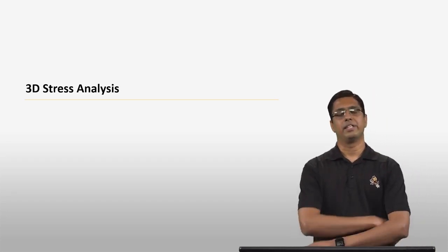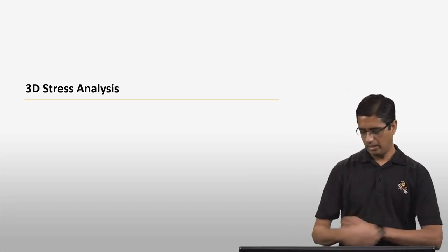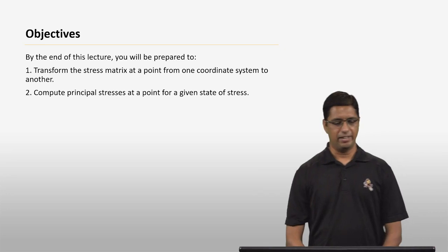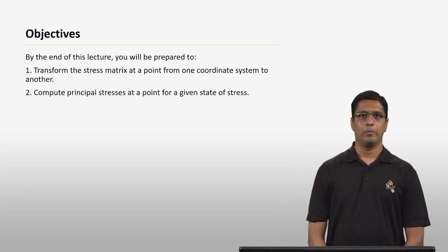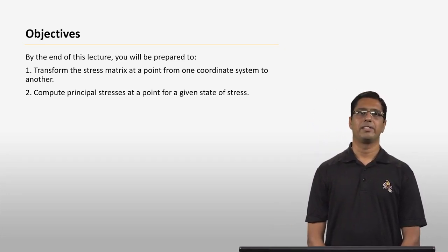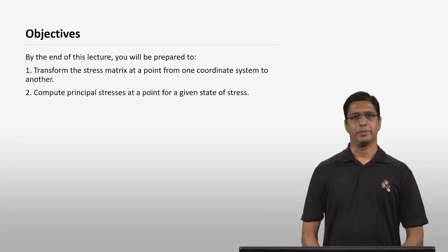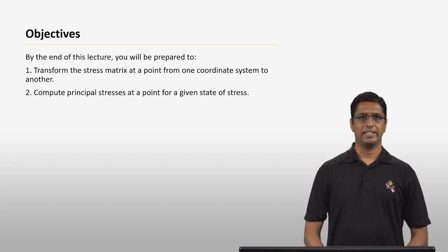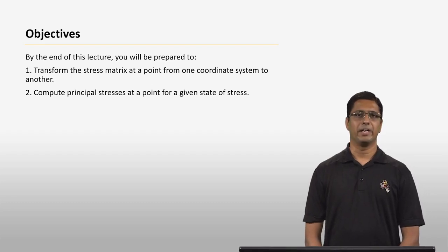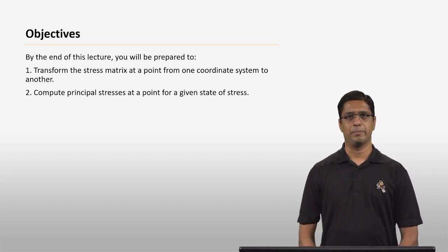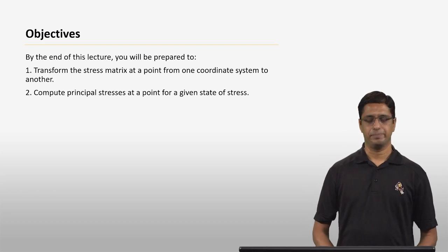So today's lecture is going to be on 3D stress analysis. And what we are going to do today is learn two things. One is how to transform a stress matrix in 3 dimensions from one coordinate system to another. And the second thing that we'll be doing is learning how to compute principal stresses at a point for a given state of stress.